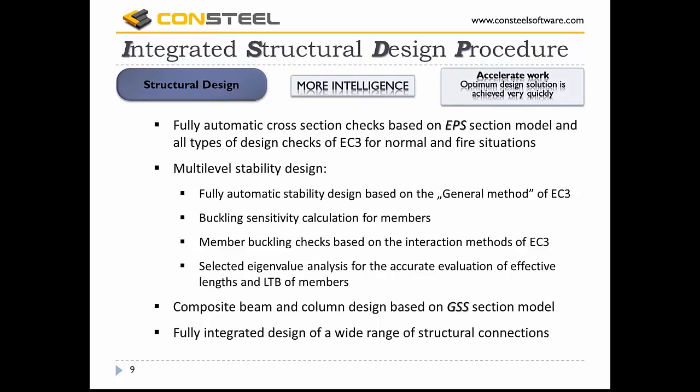There are special member buckling checks based on the interaction methods of Eurocode Part 3, and selected eigenvalue analysis for the accurate evaluation of effective length and lateral torsional buckling parameters of members using these member buckling checks.